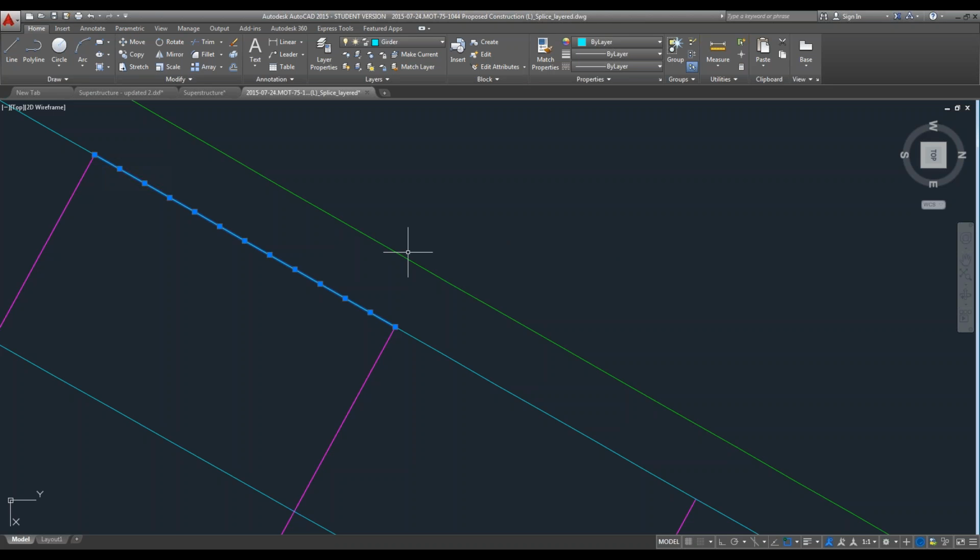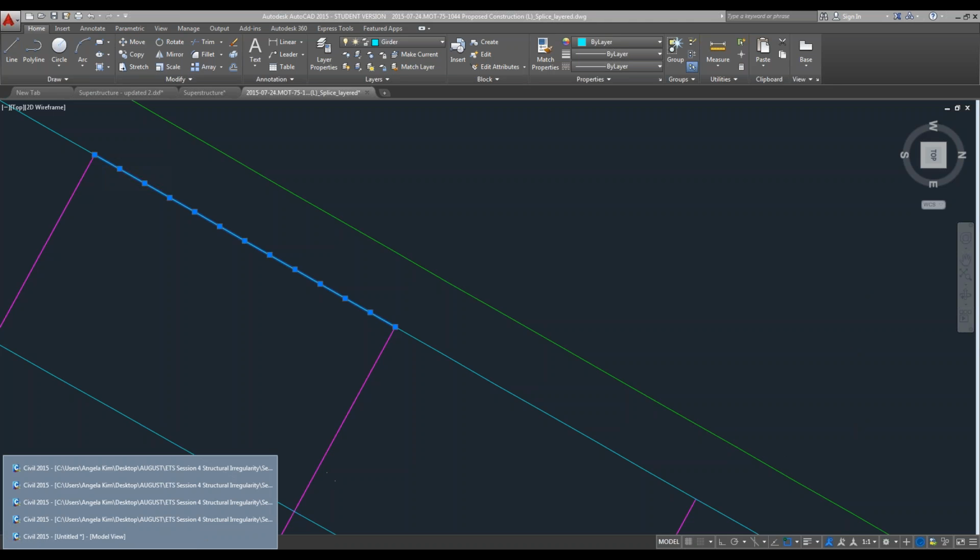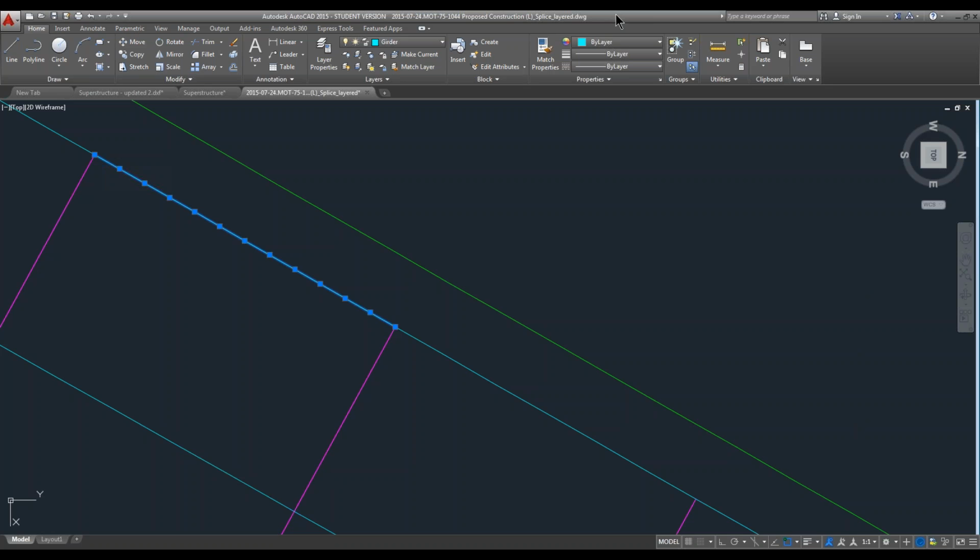However, I actually mentioned this in other trainings. Right now, as the second improvement, you can float the lane in the transverse direction. However, the lane itself cannot be floated. But what will be changed by the end of December is that the entire moving load floating, even with the lane, will be available. That's the third improvement that we're bringing to Midas Civil for the second update this year. So right now, the lane itself is fixed, but the vehicle is floated.